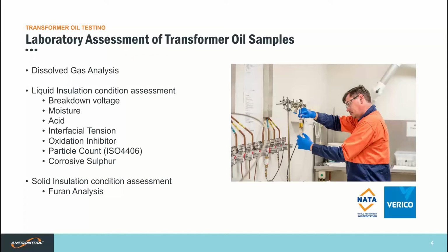oil needs to be sufficiently high to allow it to withstand the electrical stresses imposed in service, and this includes ensuring that an arc is extinguished. The moisture content of the oil should be low, otherwise the electrical strength of the oil will be impaired, and moisture can be absorbed into the paper insulation, possibly reducing paper insulation life and also increasing the risk of dielectric breakdown. Sources of moisture in transformer oil include ingress of moisture from the atmosphere, oxidation of the oil, acid catalyzed hydrolysis of paper insulation, and thermal degradation of paper.